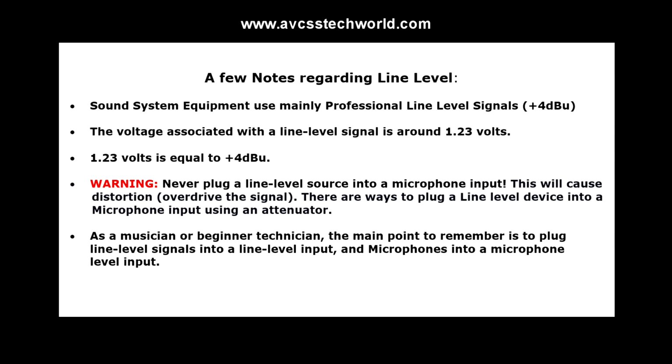Warning: never plug a line level source into a microphone input. This will cause distortion and overdrive the signal. There are ways to plug a line level device into a microphone input using an attenuator. As a musician or beginner technician, the main point here is to remember to plug line level signals into a line level input and microphones into a microphone level input.